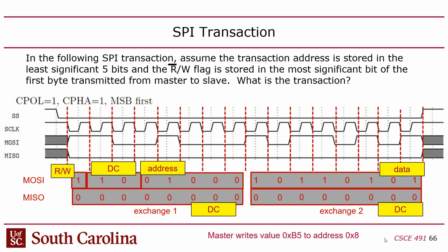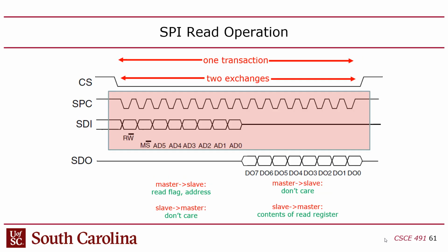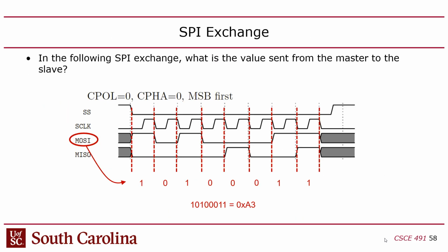Now there's an exception though. I mentioned that that first writing edge is a little weird, because notice that actually the first time I write, there is no edge, right? Because it's got a head start. This means that the master is setting the data bit before you even have a first edge of the clock, right? So how does it do that? I don't know. It just starts it out that way, right?